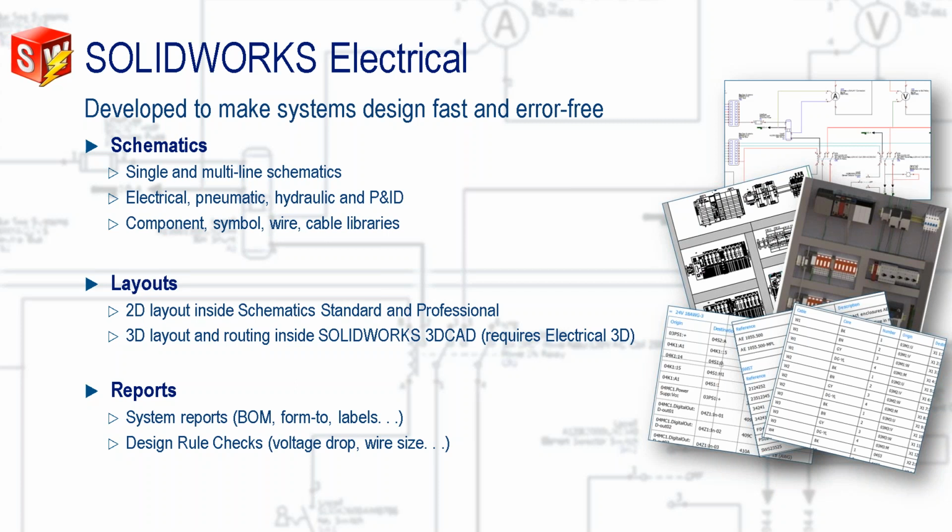Essentially, this is a project audit. We can run customized audits or out-of-the-box audits against our project and catch commonly missed errors, such as missing wire numbers, duplicated tags, over-assigned contacts, the wrong size wire gauge connecting to a terminal. Those kinds of things can be caught.